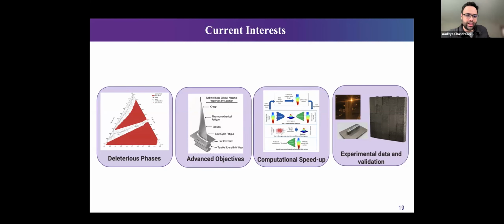The idea is that if you have composition A and composition B, and two different elements next to each other, one at composition A, the other at composition B, then in the traversal between these two compositions, you don't want to hit any deleterious phases. And so we are looking at doing an integral between these two compositions. So that's one idea that we have pushed on.